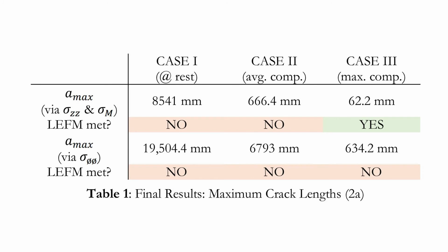As shown, the linear elastic fracture mechanics criteria were only met for the case of maximum spring compression with a circumferential crack. The other cracks required for failure would not be able to fit on this shock, and thus did not apply to this situation.